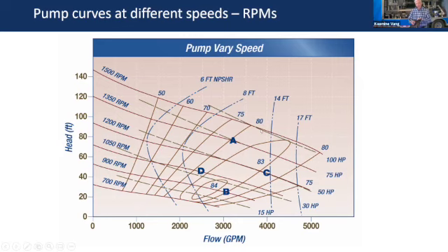And you notice these are efficiency numbers here. It says 80, 75, 70. And you see these lines that flow across, these brown lines, shows how efficiency goes. On this pump, if you slow it down here to this point, which is about 2,800 gallons a minute with about 30 feet of lift, you're at 84% efficiency. It's actually gained efficiency. This is impeller efficiency, not overall efficiency. So you see it spreads these efficiencies out, which helps you.